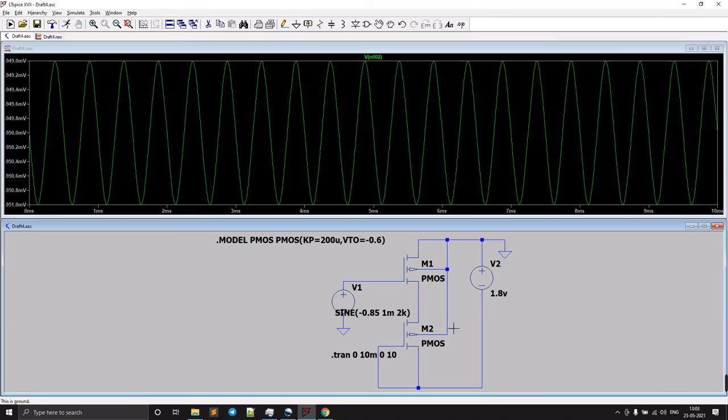But the main thing here is that without this resistor, we are using this PMOS in order to work as a resistor. Because we cannot get an actual resistor, that is a constant value, we make use of this PMOS diode connected to act like a resistor.